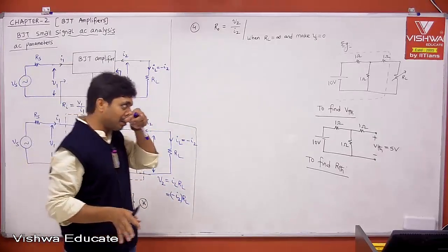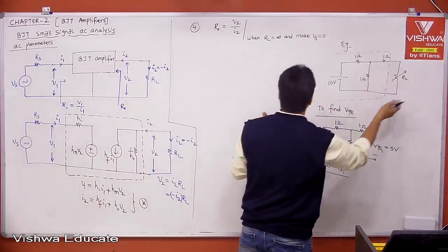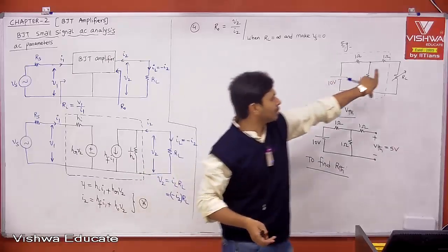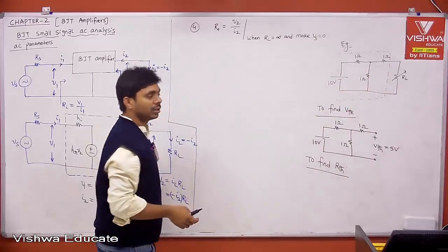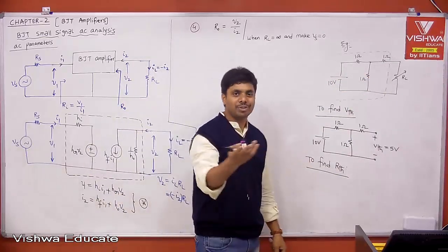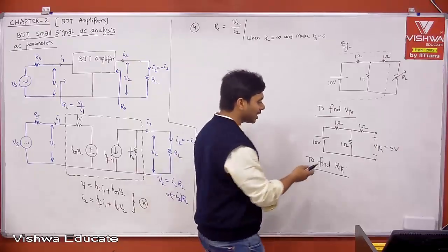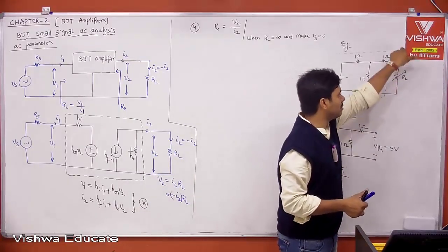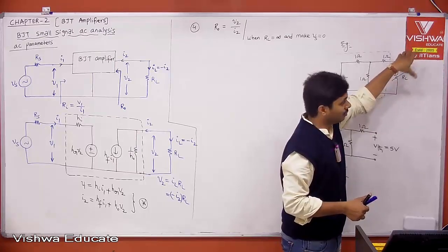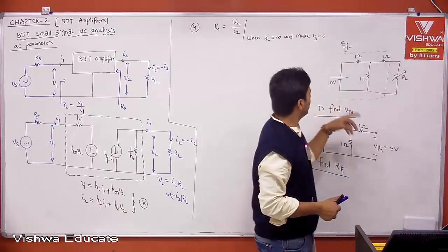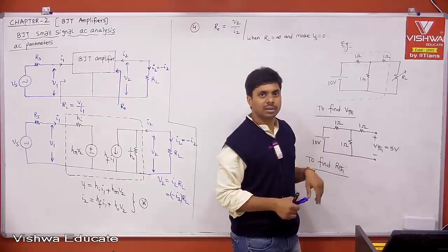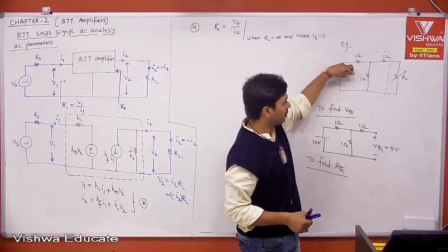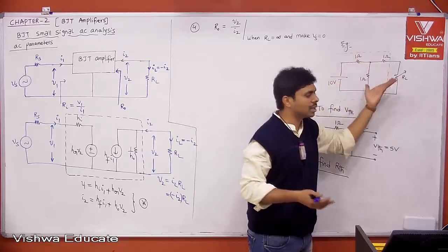Then let me come. We are excluding the load. Yes, we are excluding the load. The impedance seen from the output port. But tell me, unknowingly or knowingly, I don't know, how are we calculating RThevenin? Excluding the load, we are not applying a voltage and we are not getting a current. Remember, there is a methodology saying that if there is a voltage source, short it. Then 1 parallel 1 is 0.5, in series with 1 is 1.5, that is RThevenin.